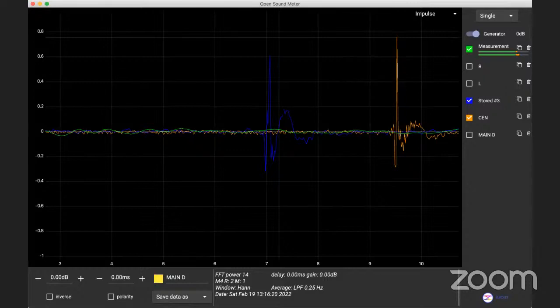And it gets all the more complicated when you're doing an Atmos setup or a 5.1, 7.1 setup, when you're setting up a movie theater and stuff. So all this time delay is very important when you're using multiple speakers. And then SPL also, to make sure that everything is playing at the right SPL. Okay, it's a complicated dance basically, and it requires practice to get it right.